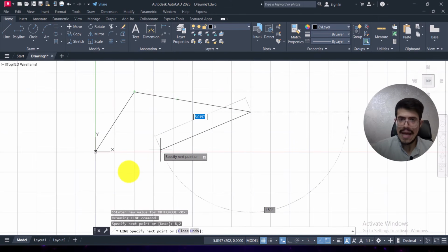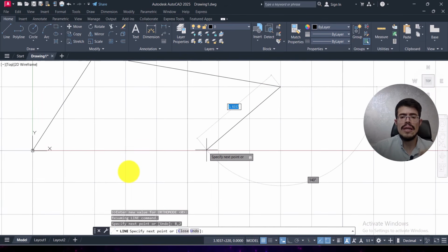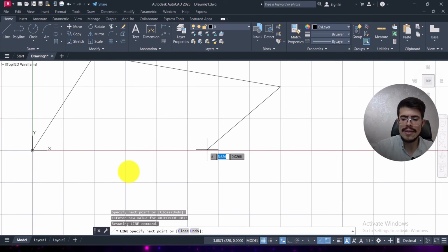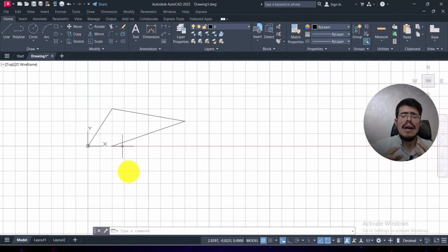It's absolute. Now, to see if it's working in an absolute manner correctly or not, we again hold shift with number 3 to activate the sharp sign. In here, again, I say I want to go to point 2 and 0. I say 2 comma 0, enter. Now, as you can see, I'm in my absolute coordinates. I think it's enough to talk about the absolute coordinates.